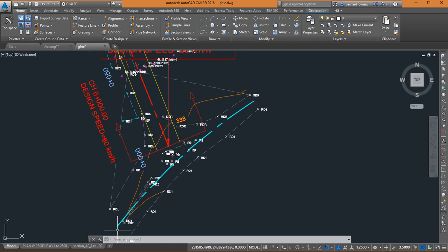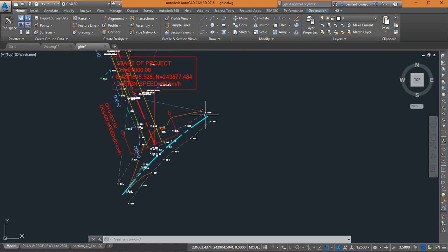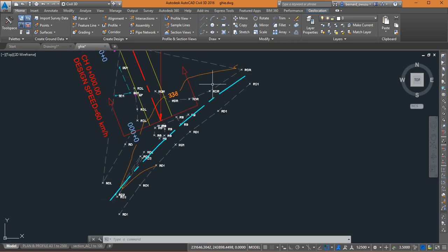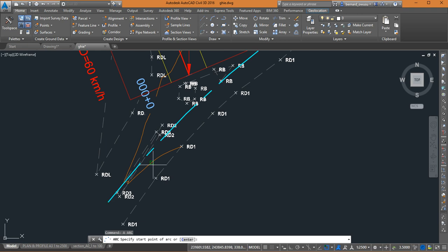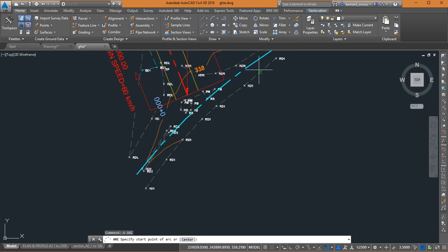And I said there is more to what we are doing, but we are going to do a basic intersection. So at the start here, draw a simple AutoCAD arc to define this particular alignment. Type A to define an arc. Then you click on the start, where you want it to pass and where you want it to end. Have you done that? Those who just came, have you been able to do it?